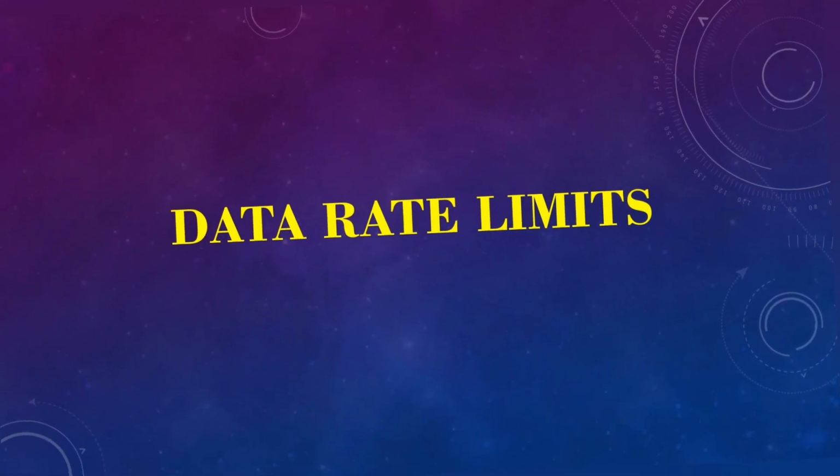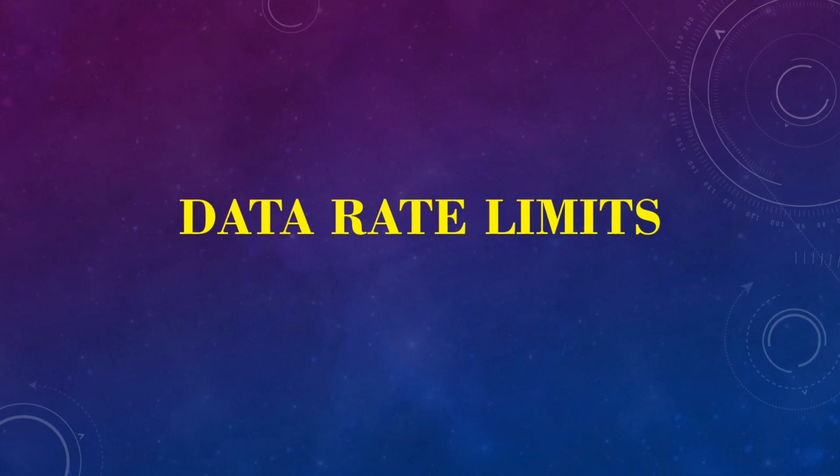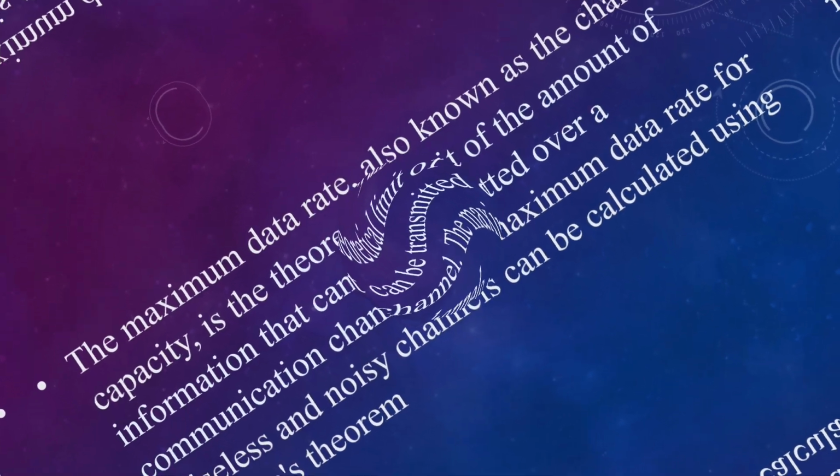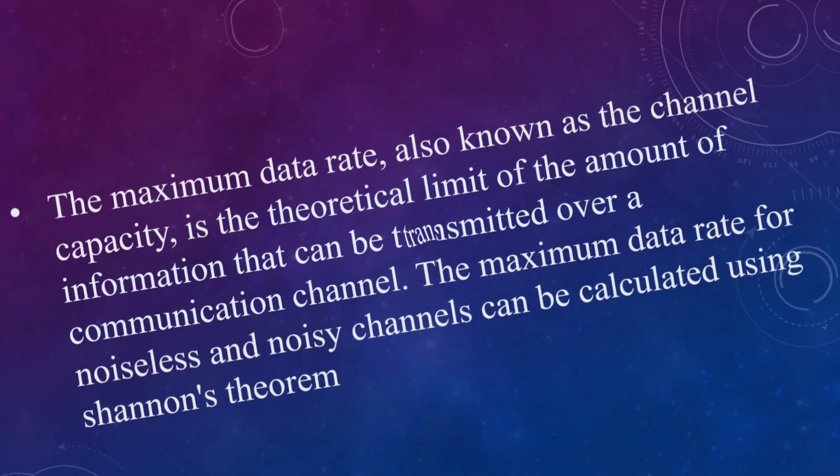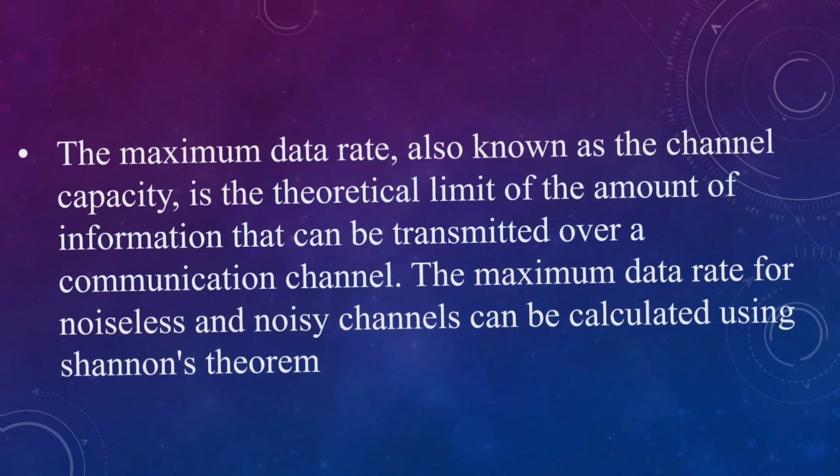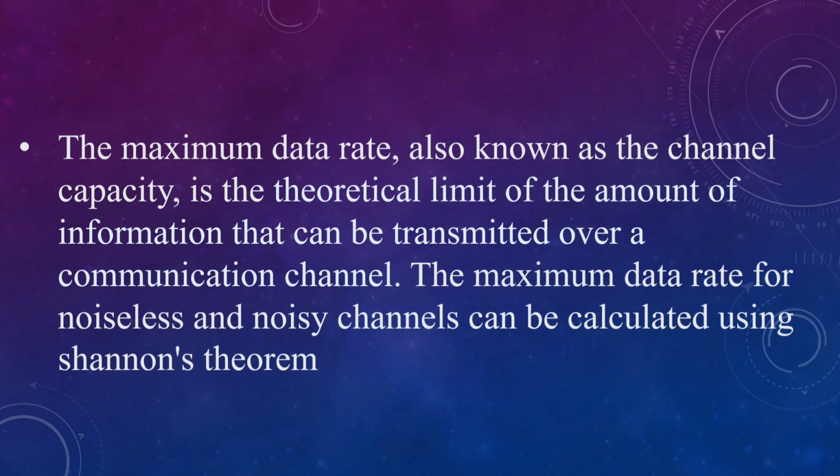Now the second last point is data rate limits. The maximum data rate, also known as the channel capacity, is the theoretical limit of the amount of information that can be transmitted over a communication channel. The maximum data rate for noiseless and noisy channels can be calculated using Shannon's theorem.